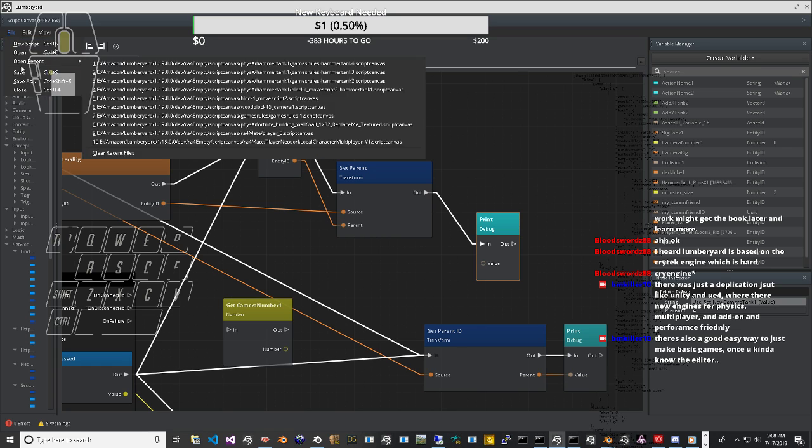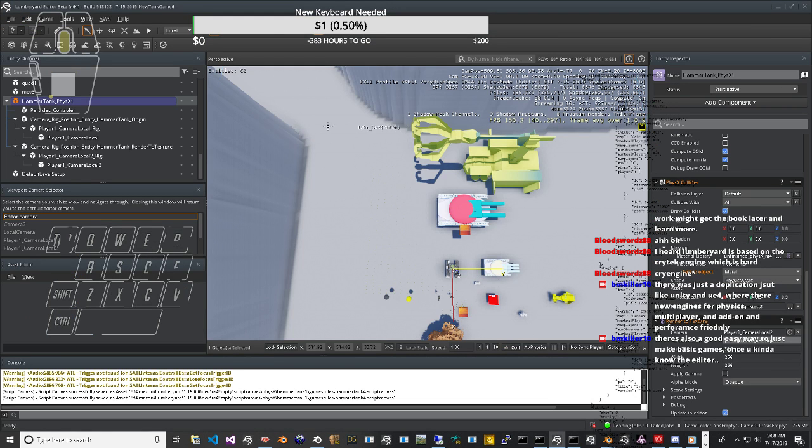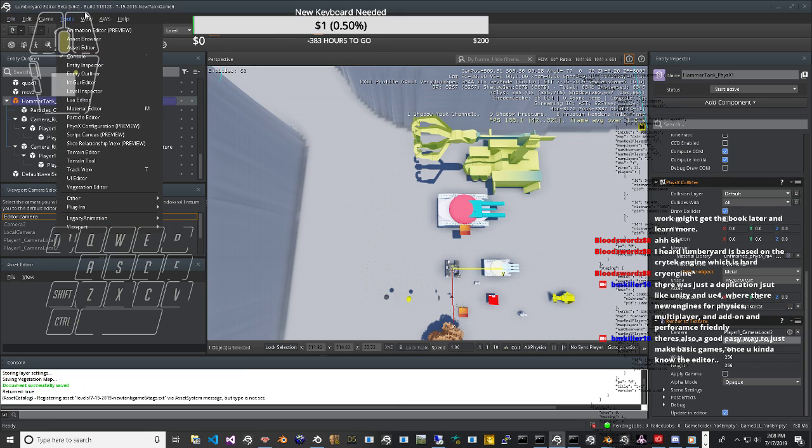Let the unloaded, natural radius of the pneumatic tire be r, also the radius of the equivalent solid tire. If the hub has velocity v, the solid tire spins with angular velocity v/r. Since the loaded radius of the pneumatic tire, RL, is smaller than r, v/RL, the angular velocity of the loaded pneumatic tire, must be larger than v/r.